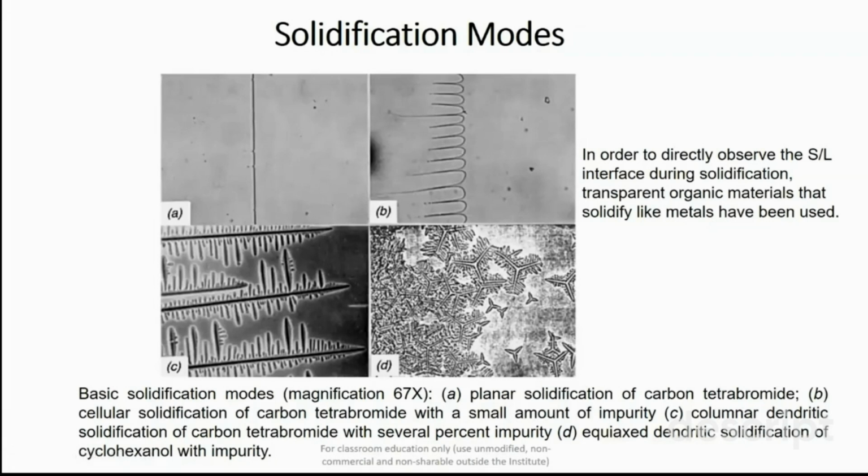They are formed due to the instability of the solid liquid interface, because more and more of the solute is getting rejected into the liquid melt, and the heat ahead of the solid liquid interface is conducted away. So that makes the solid liquid interface become unstable, and then the planar solidification front, in case of the alloy composition, when solute is getting rejected, further breaks into the cellular type of solidification front or the dendritic type of microstructure.